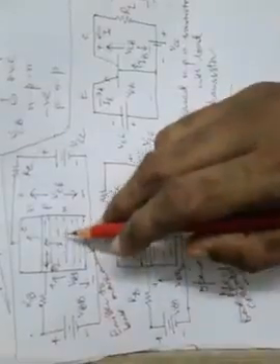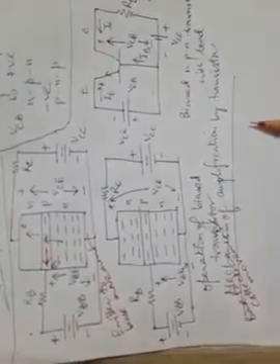So as a result, the lifetime of the electrons injected from the emitter side and passing through the base area will be much higher, and for them the chances of recombination will be very less. So more and more electrons will move inside the collector region easily without being recombined by the holes at the base area.